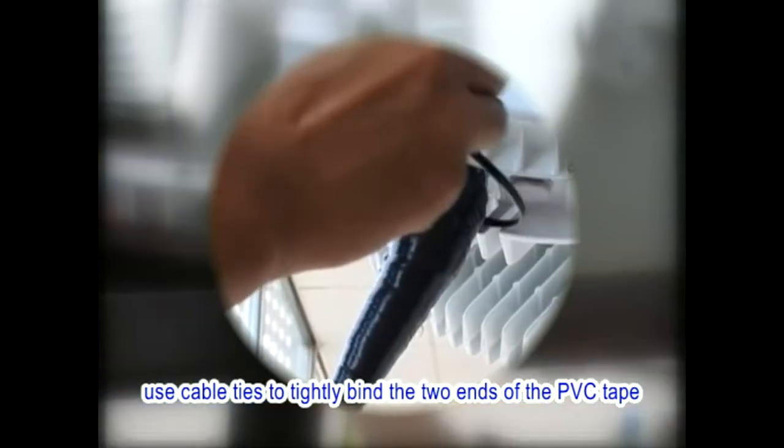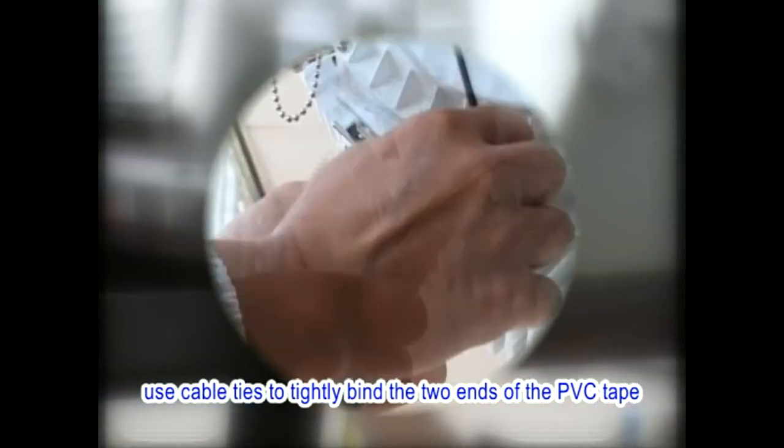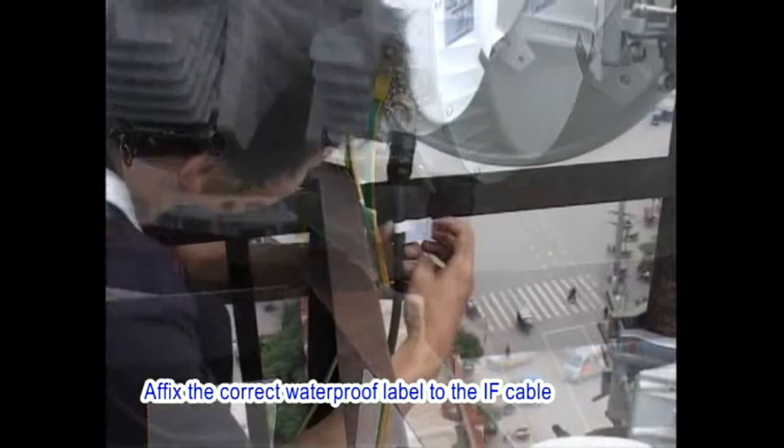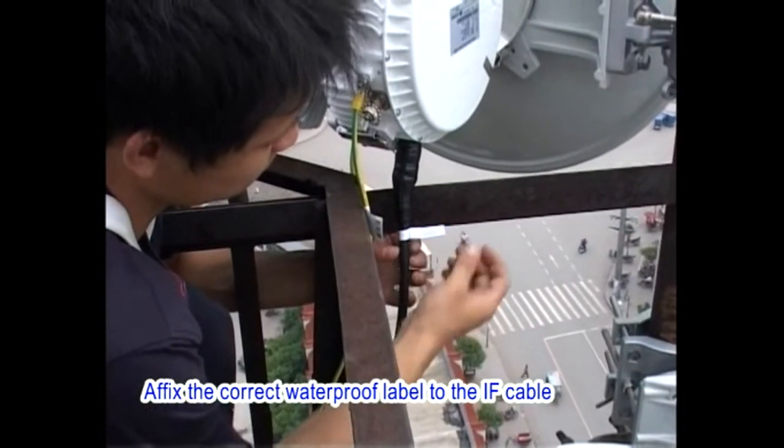Finally, use cable ties to tightly bind the 2 ends of the PVC tape to prevent the PVC tape from becoming loose. Affix the correct waterproof label to the IF cable.